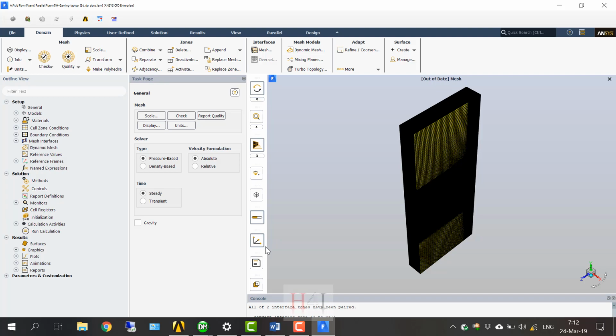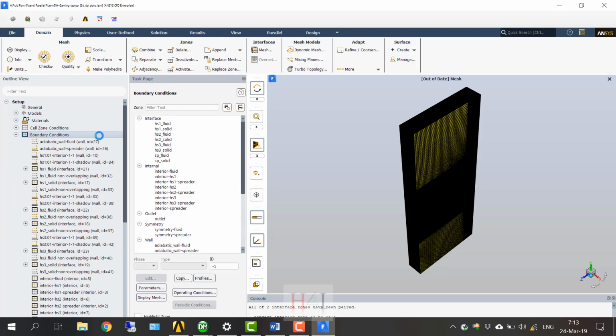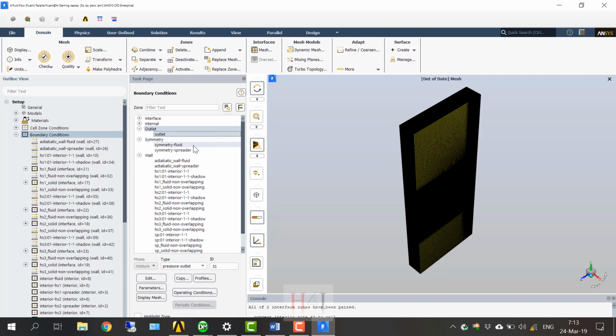Okay, if you found that there is no temperature transfer to the fluid, then there is something wrong with the interface. Between the solids, as I said before, they are a single part, so I don't need to create an interface. I think there are some interfaces with fluid. No, not interfaces, internal regions. These are the interfaces I created now. These are interior regions. Okay, I didn't see it. Not interface.